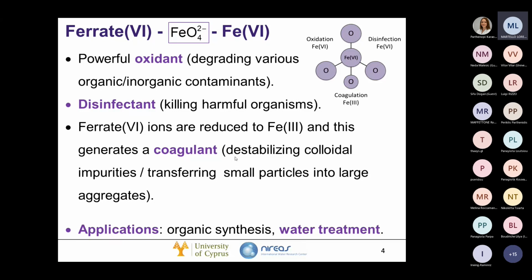And another feature of iron 6 is that after its application it is reduced to iron 3, and iron 3 is a common coagulant in wastewater treatment. So basically we can have 3 actions with one chemical, and this is oxidation, disinfection, and coagulation.